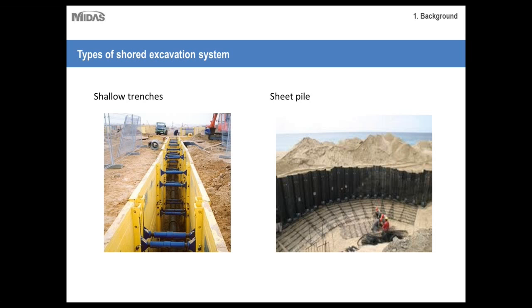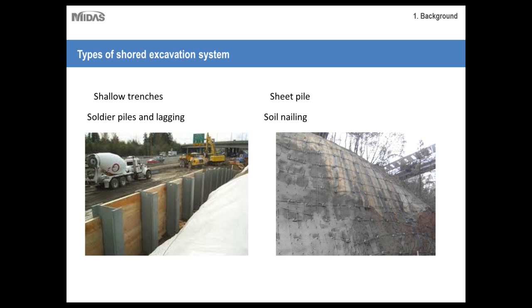And in these couple of slides that will be following, we'll be talking about what are the different types of shoring systems. I'll not be talking about where they are used and why. That is something we'll be discussing in the following chapters. Then we have soldier and lagging supporting system, where we have vertical steel pile members that are drilled into the ground, and we have timber or concrete laggings in the transverse direction to provide the support to the excavation.